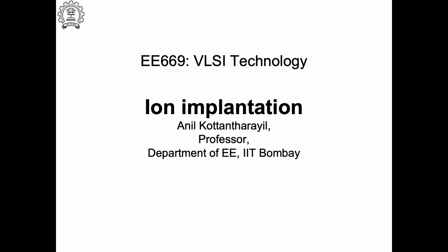Yesterday we started the discussion of ion implantation, right? So today we'll continue that. As I mentioned, ion implantation is the preferred process for doping for VLSI manufacturing, and the main advantages are that you can easily mask this using photoresist, because you don't have a high temperature process for introducing the dopants into the silicon. That gives a big advantage, and also you can precisely control the total amount of ions or dopants introduced into the silicon.